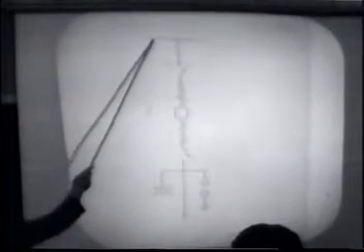We keep talking about a bus, which here is just a line. Physically, that would be tubing, cable, supported on insulators of some type. Could be bus bar, fully insulated, depending upon the type of substation.